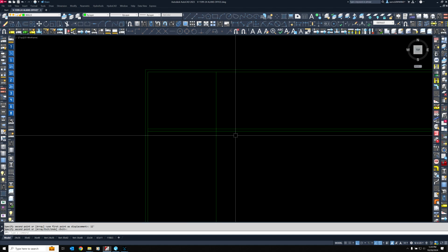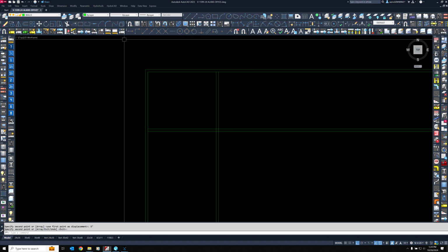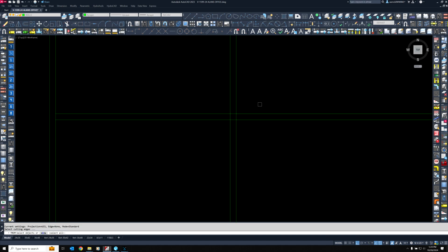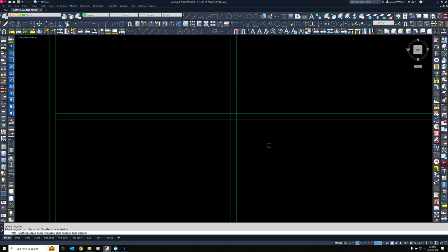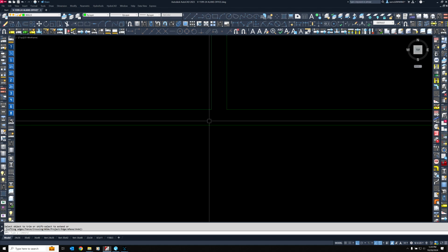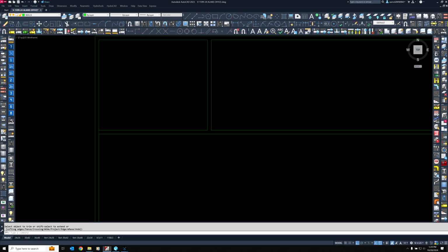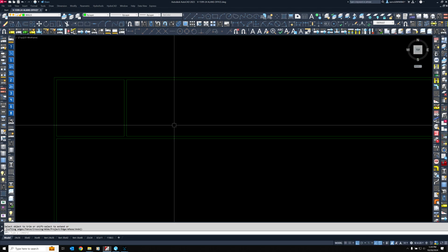All right, now we need to clean this up a little bit. We're going to copy another 5 feet because we have a real wall. I say 5 feet, 5 inches. And let's trim this back. Use the scissors. Don't double click too much. Let's use our scissors. Pick all of this. Let's cut this out. And then right here, we're going to select it all in my window and then pick the pieces we don't want. That's something that you will get real fluid with when it comes to cleaning up a drawing.